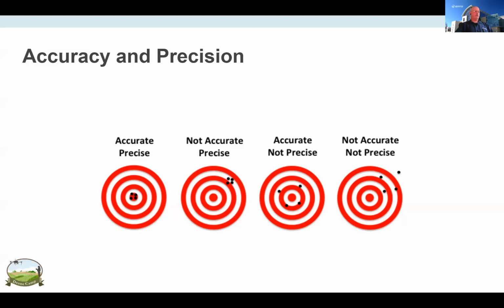It turns out that when you get down to the very fine scale and you're getting repeatabilities on the order of centimeters, and you're doing long-term mapping projects where you're comparing data from now to that collected 10 years ago, and you're in a place like California, things are moving anyway. So what the true coordinate of a feature or a location is actually changes through time. And so it's really that precision is the most important thing for us as opposed to absolute accuracy.